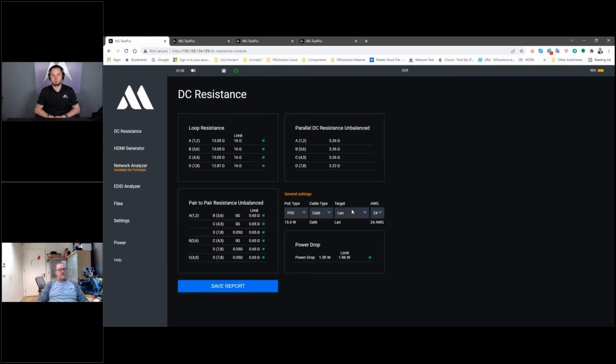Especially on spec 1, it is about 12 meg, and on spec 2, it was increased. On spec 3, it's even increased more. So it's still an asymmetric link, and we cannot treat it the same way that we are treating LAN. Additional very important comment is that HDBaseT doesn't have retransmission. So how will it overcome the differentiation on the cable itself?